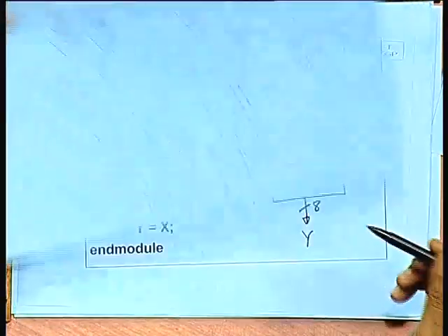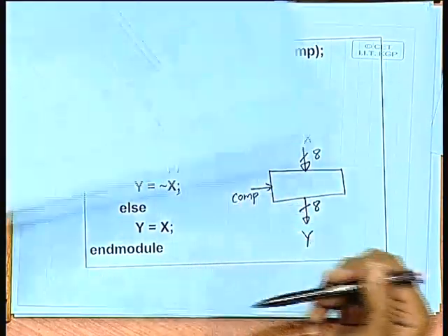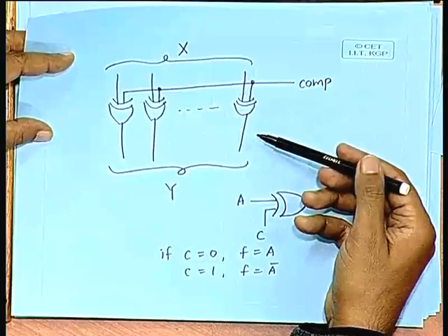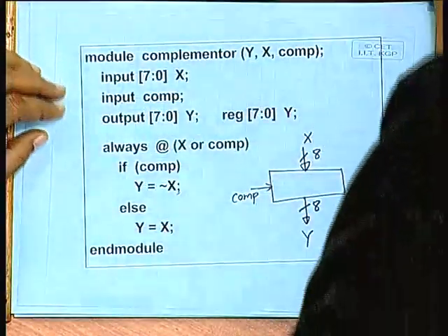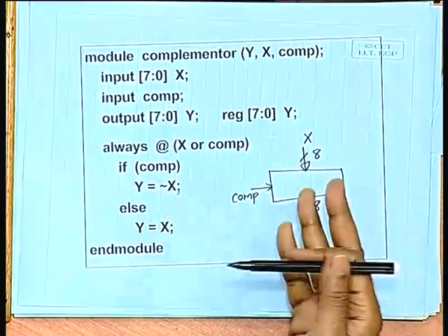So actually, when the synthesizer analyzes this code and tries to synthesize it, the logic functions generated after analyzing this will all be XOR functions. So, the synthesizer will be intelligent enough to synthesize it as an array of XOR gates typically. Okay.